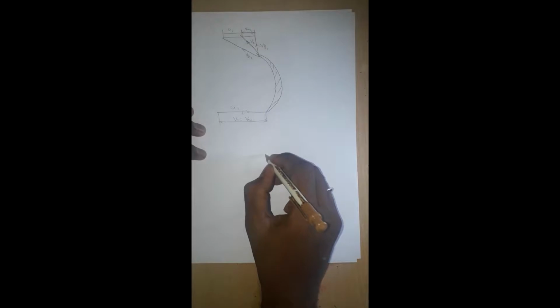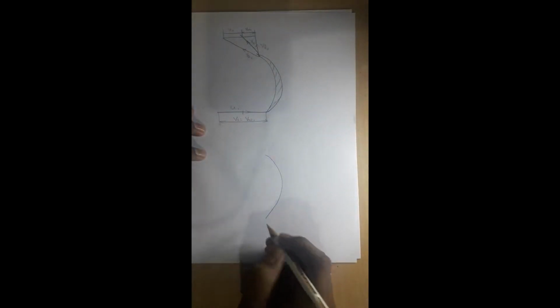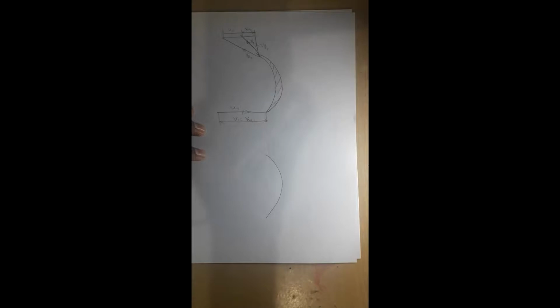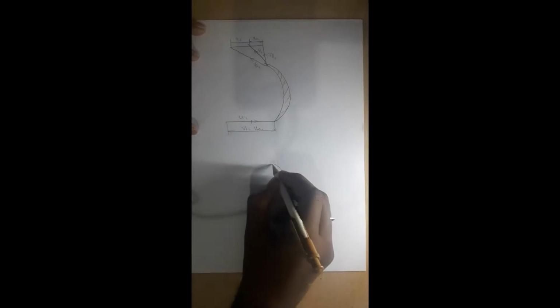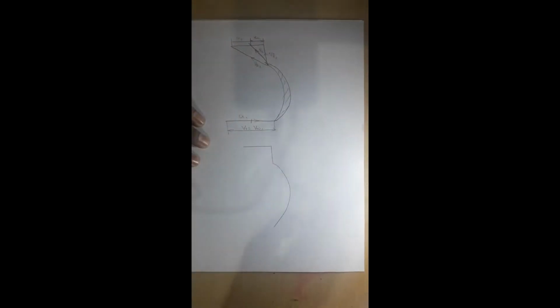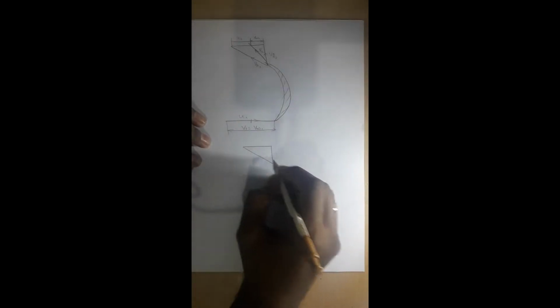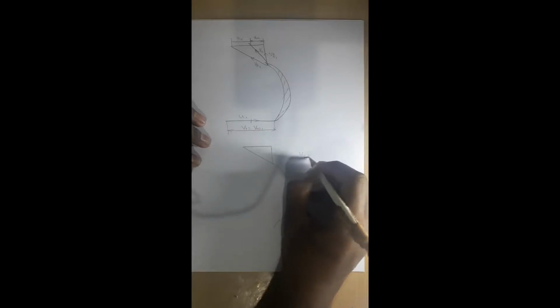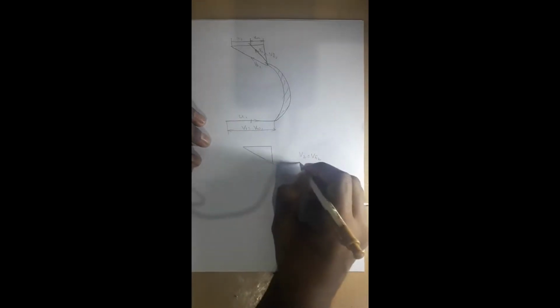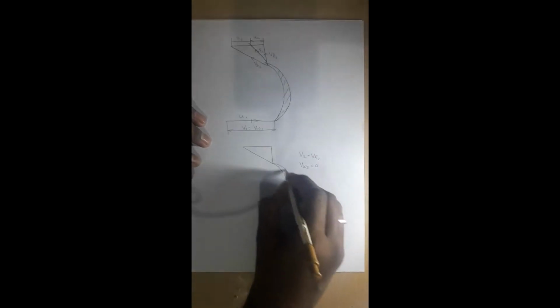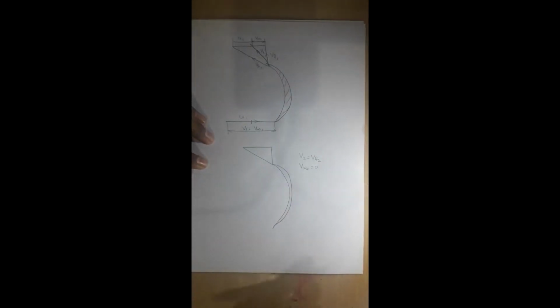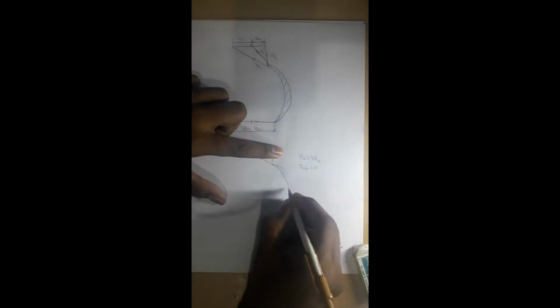Similarly, for a Francis and Kaplan turbine, the velocity diagram will have a slight deviation, because they are radial flow. On the output, there is no radial component, that is V2 will be equal to Vf2, that is Vw2 will be equal to 0. So we will draw it neatly.